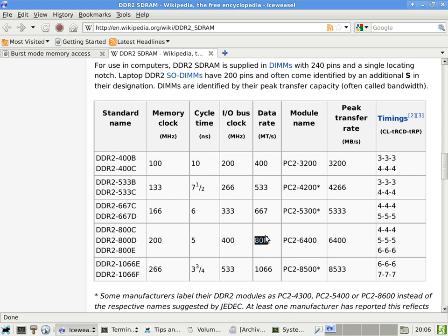And that's not just with the ATA bus, it's also with the PCI bus. PCI Express is quote unquote serial, even though you can specify one. Do we have a 2-lane PCI Express bus? 1, 4, 8, or 16. Okay, so they skip 2. But it's for the most part a serial scheme instead of a parallel scheme. Okay, so that's a kind of interesting question, but the answer has to do with all these different factors for designing a motherboard.